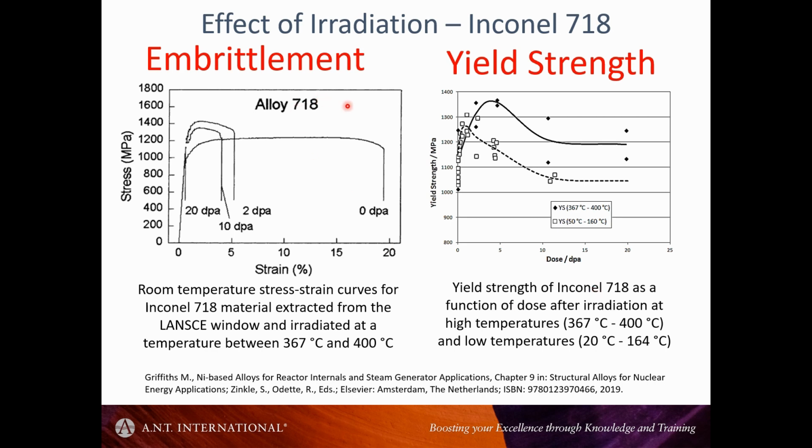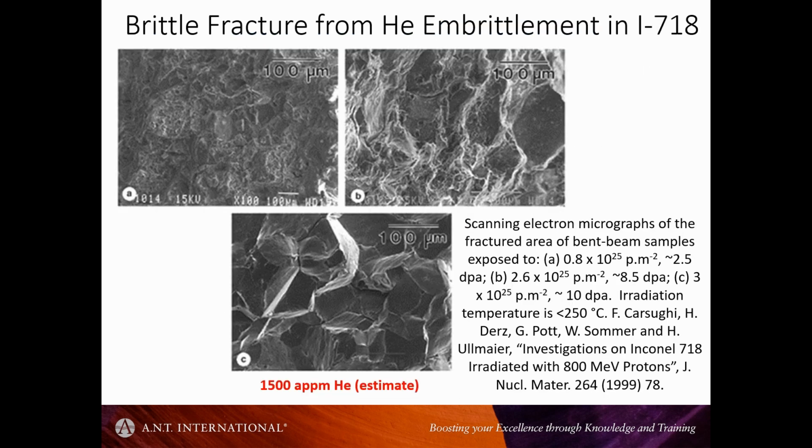Another thing which is common in Inconel material, especially at high dose, 20 dpa in this particular case, is embrittlement. And you can get conditions where the ductility is basically gone. This particular instance, although it's not proven in this case, is probably linked to helium. So that embrittlement is shown here in terms of the fracture surface. This is Inconel 718.